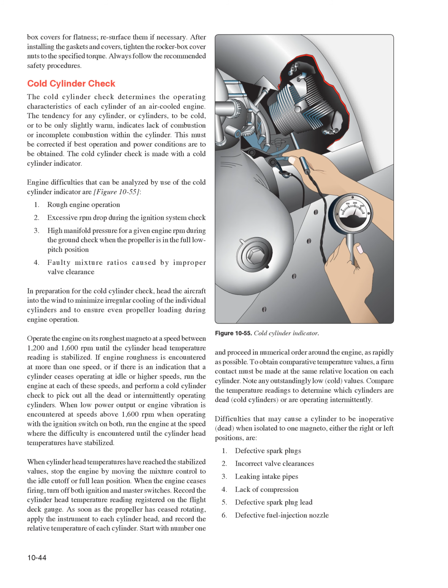1. Rough engine operation. 2. Excessive RPM drop during the ignition system check. 3. High manifold pressure for a given engine RPM during the ground check when the propeller is in the full low pitch position. 4. Faulty mixture ratios caused by improper valve clearance. In preparation for the cold cylinder check,